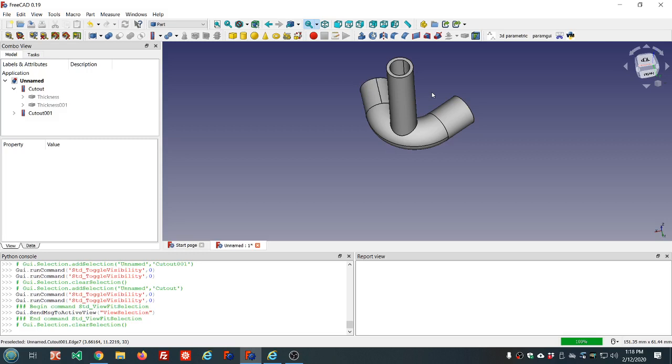The attachment is something that you use very commonly in Part Design with sketches. We'll often, almost always, attach a sketch to something, usually one of the major planes: the XY plane, the XZ plane, or the YZ plane. And we'll cover that as we get to it. We also covered today using the cutout tools and showed how they can be convenient for connecting walled objects together.